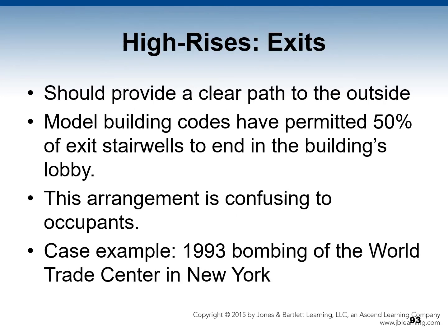In terms of exits, they should provide a clear path to the outside. Model building codes have permitted 50% of exit stairwells to terminate in the building's lobby rather than outdoors. This arrangement is confusing to occupants. One case example: during the 1993 bombing of the World Trade Center in New York, the lobby filled with smoke, making the exterior door impossible to find for trapped occupants on the mezzanine level.